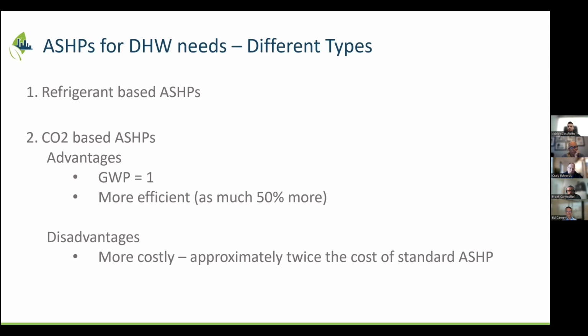The other reason we like those systems is because they're high pressure, so they need a different type of compressor. They use reciprocating compressors, which are kind of like a car engine, and they're really durable. We don't have direct experience, but they're built to last 25 years, instead of these smaller heat pump systems with scroll compressors, where we're already finding failures in less than 15 years. So we're enthusiastic about CO2 from a durability perspective as well.